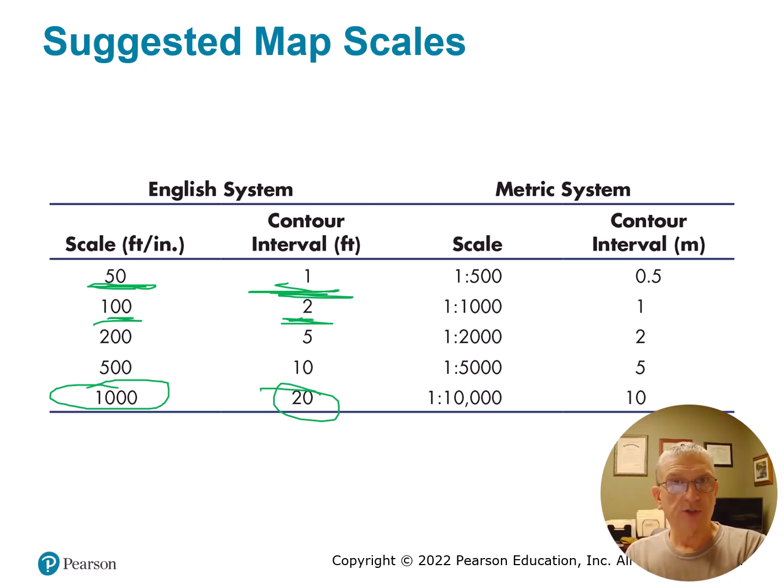You're going to be about 2 inches square, and 98% of your drawing is going to be blank paper or notes. Don't flood a drawing like that with notes when you're trying to draw attention to the property or the project that you're drawing. You probably want to do that at 1 inch equals 20 or 1 inch equals 30, so that it makes a larger impression and jumps off the page, but mostly so that you can get more detail. If all it is is a 4-sided plat of property with no structure, setbacks, contour lines, or anything else, then draw to whatever scale you want to. You don't have any extra detail to provide. But if there's any detail to provide, make sure that your sheet size accents it.